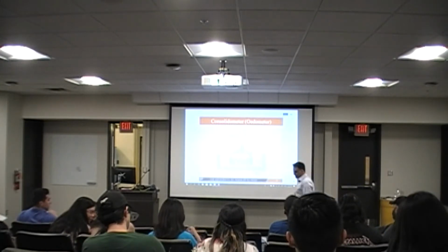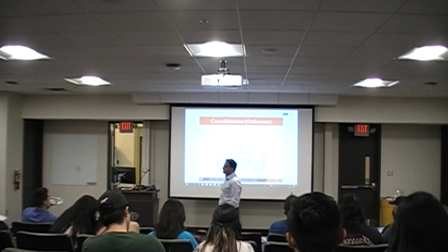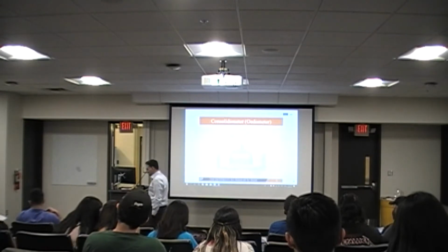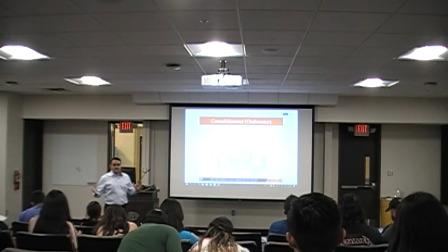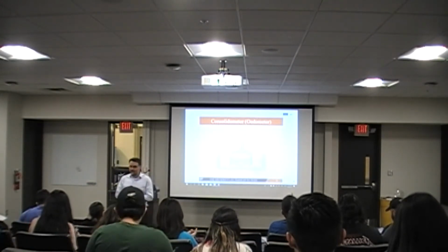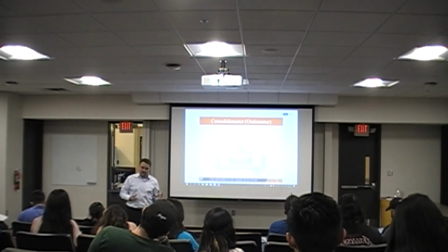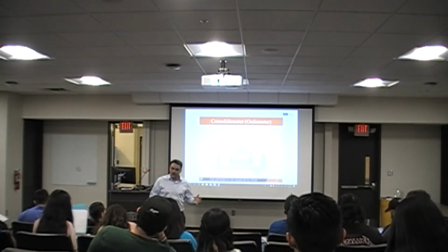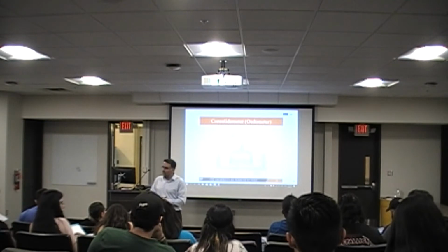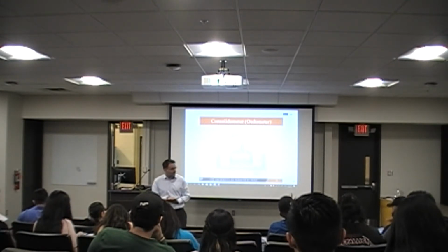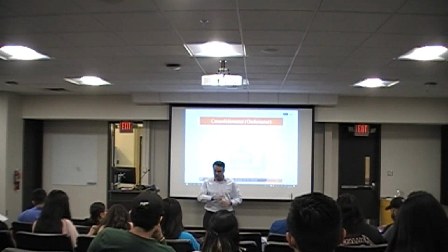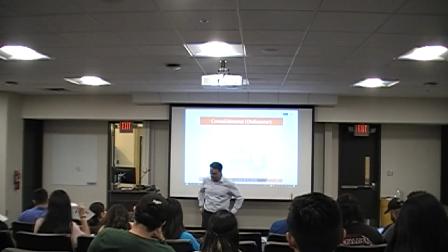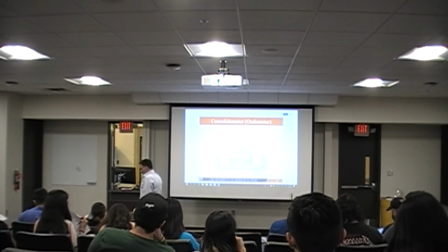So that's what we talked about in the previous lecture. Also, we talked about the different types of settlement that we have. Remember, we talked about immediate settlement, and we talked about time-dependent settlement. Immediate settlement is independent of time. Time-dependent settlement is obviously a function of time, right? Immediate settlement means as soon as I apply the load, the deformation will take place beneath the loading condition that we have. Oftentimes, we have vertical stresses or vertical loads, and the deformations are also going to be in vertical form. All right, so that would be the immediate settlement.